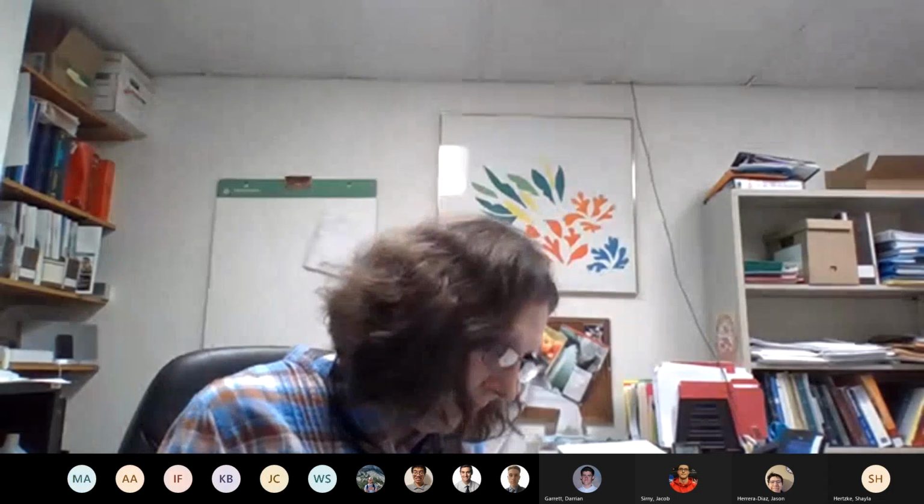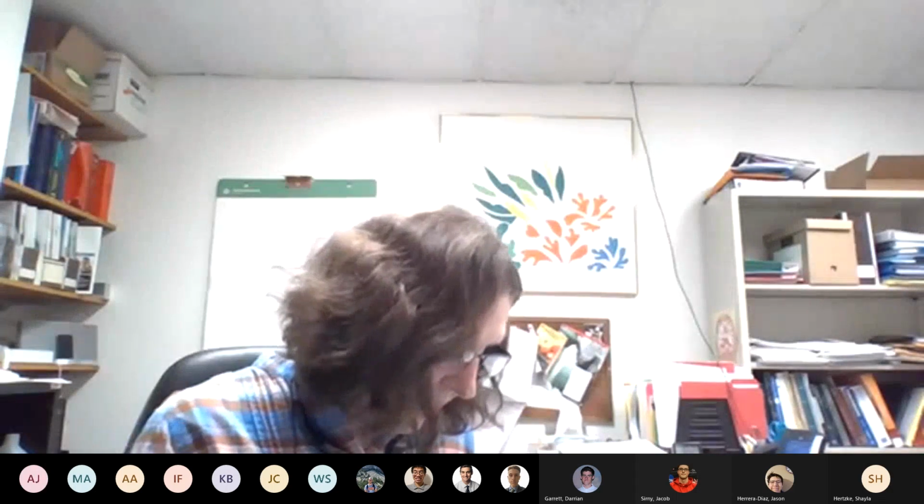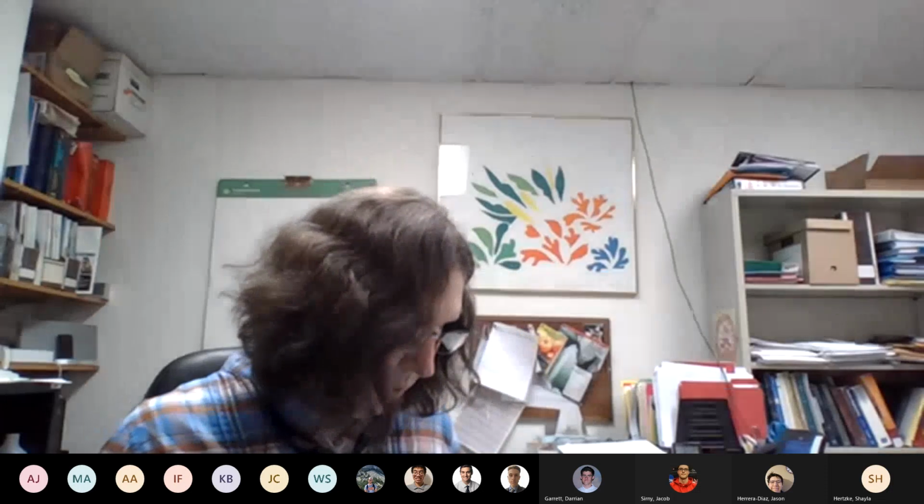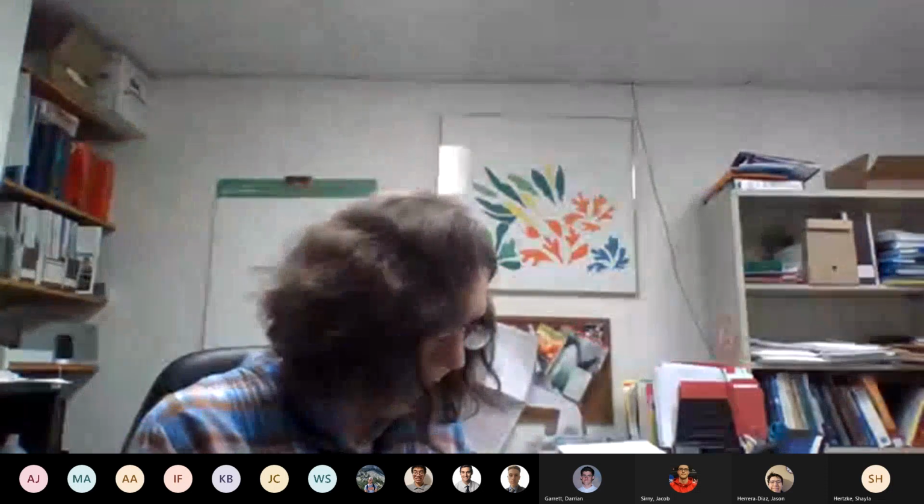So a sheared edge has a distinct side. Also, it's really important to recognize that it is not straight, so there is sort of an angle to it. Again, we have the burr. Now, we did say that clearance was important. Proper clearance is related to sheet thickness and ductility of metal.